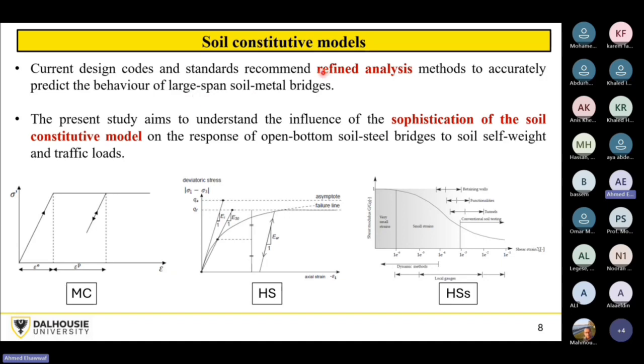It only recommends that if you are going beyond a 10 or 11 meter span, you need to do refined analysis, meaning that you have to do finite element or finite difference. So if you must do finite element modeling, we have to see which is the best model that can be employed to simulate the behavior of the soil.